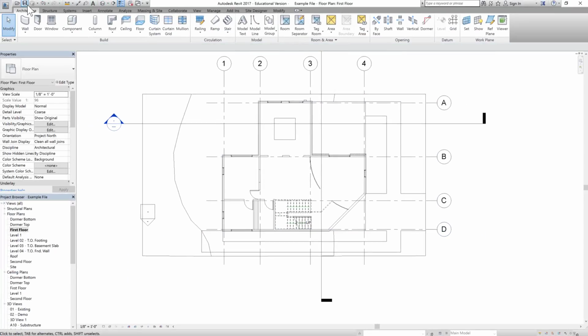Okay, what we will do now is we will save this, and the way it works in building information modeling is that when we model this building, we model this building as a design team. So we were the architects when we model this. So just imagine that once this architecture model is complete, this model will be kept or put on a server, on a cloud, where mechanical consultant, electrical consultant, or plumbing consultant or structural consultant can link to this model. They will not be copying this. They will be linking to this model so that they can put just mechanical, electrical, plumbing or structural elements.